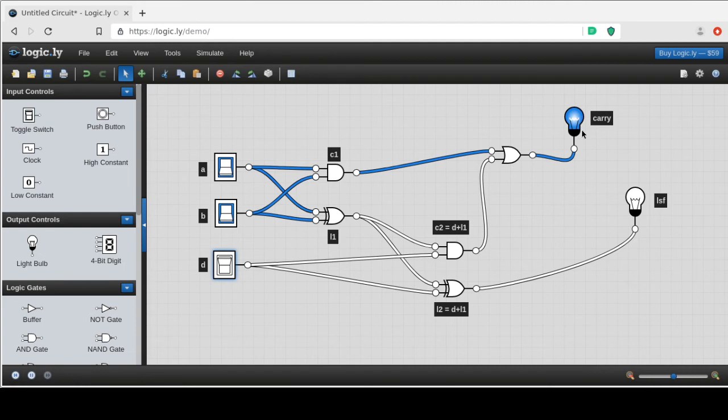And the same thing, doesn't matter the order. As long as it's 2 1s and a 0, it doesn't matter what the order is. So right now I have 1 plus 1 plus 0. We could do 1 plus 0 plus 1, and it's still 0 carry 1. And we could do 0 plus 1 plus 1, and it's 0 carry 1. The last possibility out of all 8 of them is 1 plus 1 plus 1, and 1 plus 1 plus 1 is 1 carry 1.